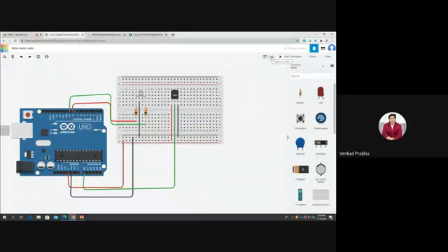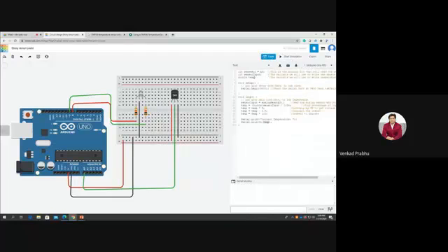Now we have to touch the coding. So go to the code. So here we have two outputs. So red, I am declaring the variable red for red color, and red I have assigned to pin number 8. So equal to 8. And int, I used another one for the color green. So the variable name is green. You can give any variable name. For my understanding, I am giving green, and that is on the 9th pin. So here I have to initialize it.